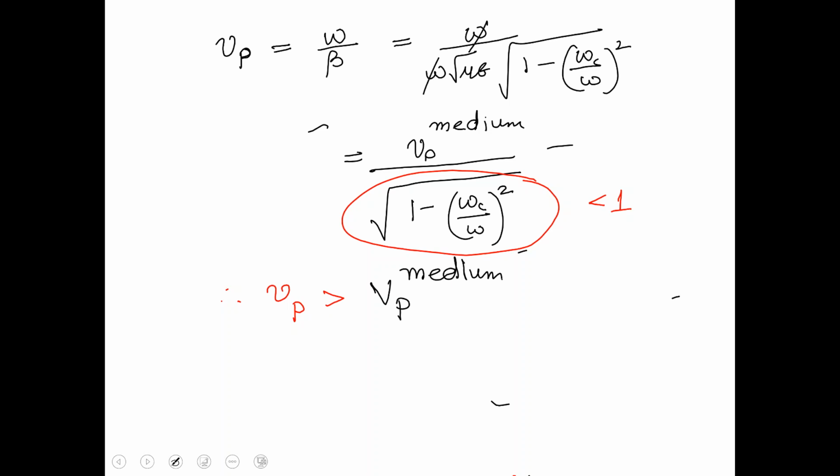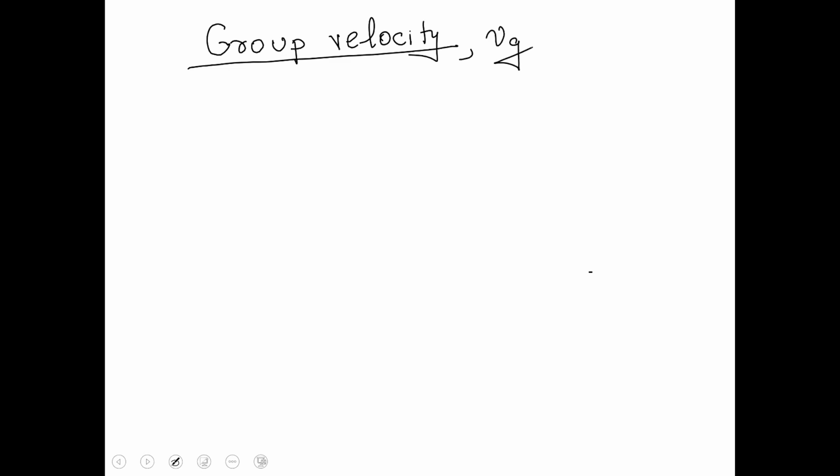No, because energy is not traveling at phase velocity. Energy is traveling at group velocity, and that group velocity is given as 1 by d beta by d omega.